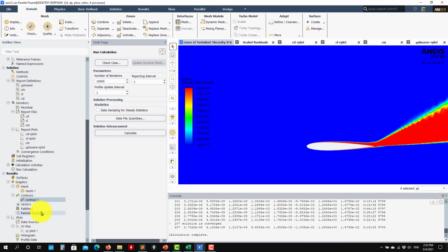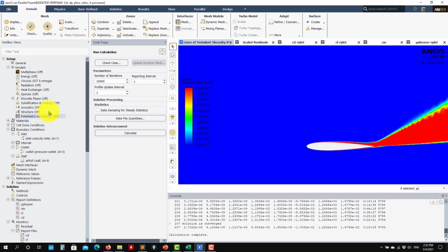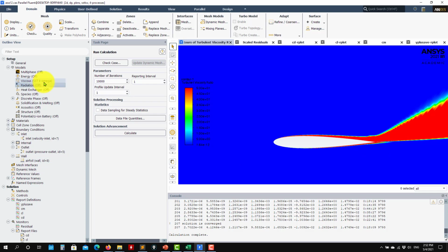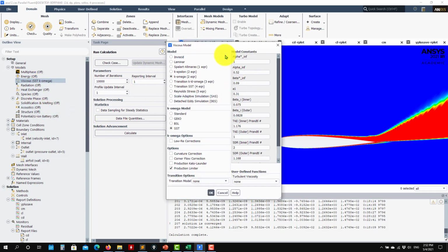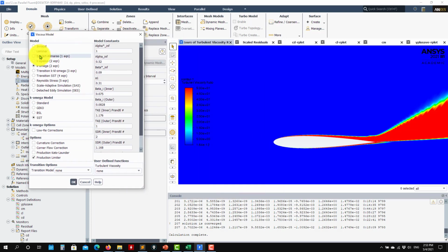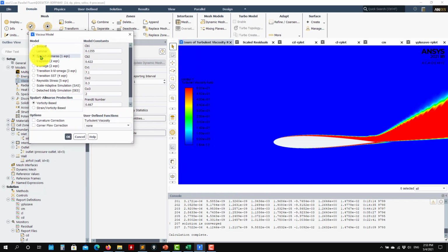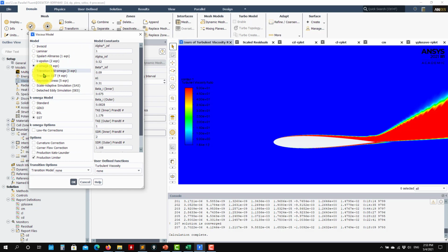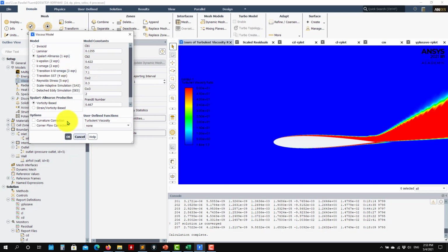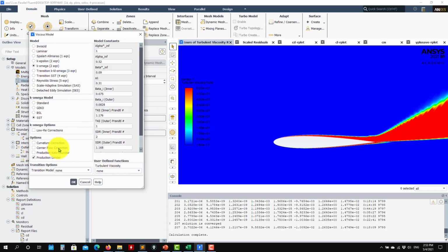What you can do is a sweep of all angles from 0 to 20 and do the validation. Also, you can test different turbulence models. This is a beautiful case because you can try all models and see the influence. It will be a small influence in this case, so you can try all of them. Generally speaking, for external aerodynamic airfoils, the models to use are Spalart-Allmaras or the K-omega SST. Later we're going to address transition in another tutorial, and also these corrections using some airfoils.